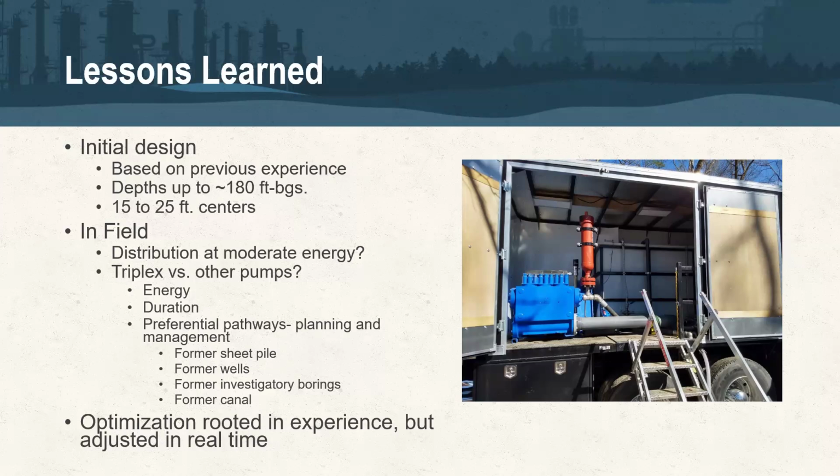We spent the first couple days working on shot volume and flow rates to affect distribution in the subsurface. And we were confirming that distribution in the subsurface by using temporary wells, implants, piezometers to monitor distribution via changes in geochemical conditions.